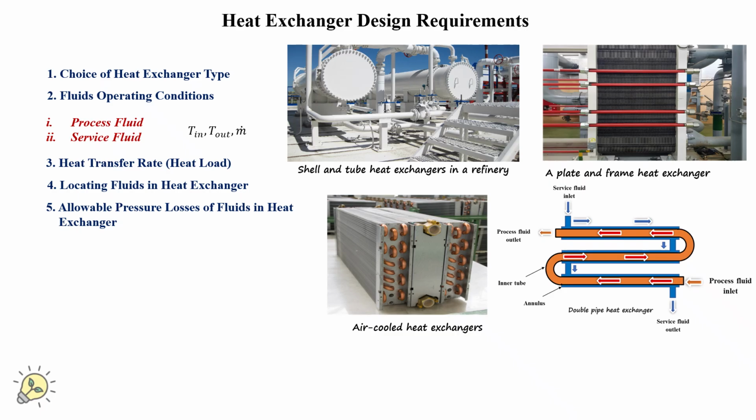Then allowable pressure losses of both fluids through the heat exchanger, because that will be reflected as a power on the pump, which should be used to circulate these fluids. And then what are the expecting fouling resistances on both sides, because usually during operation there could be another factor which is added to the thermal resistance of the heat exchanger and should be considered.